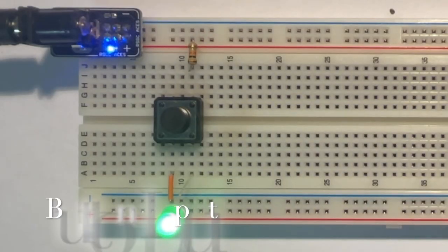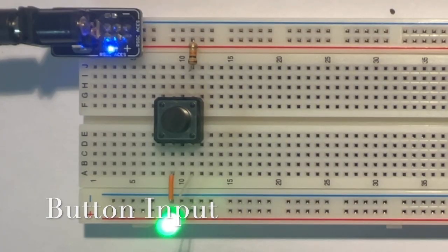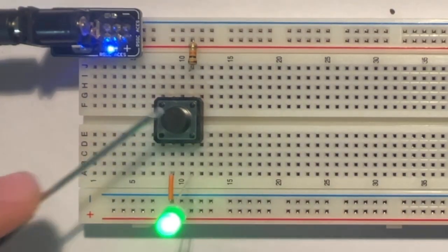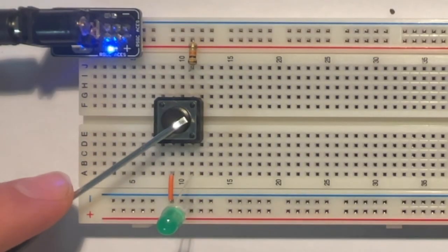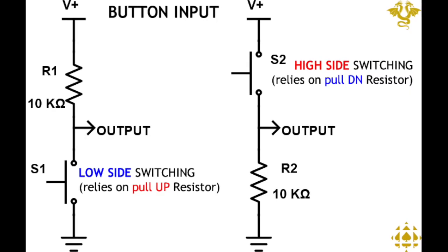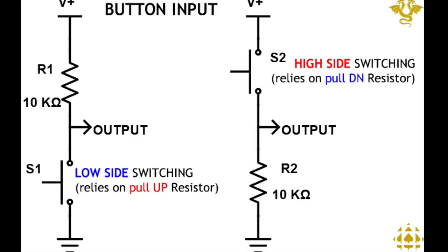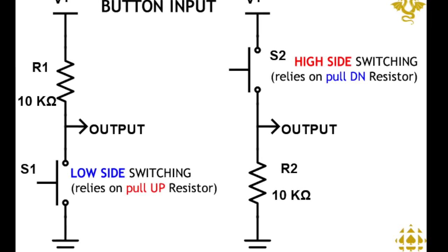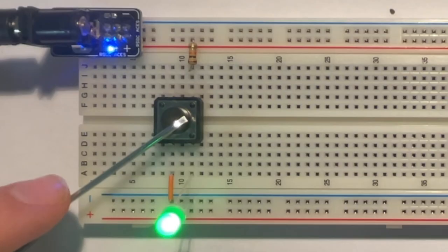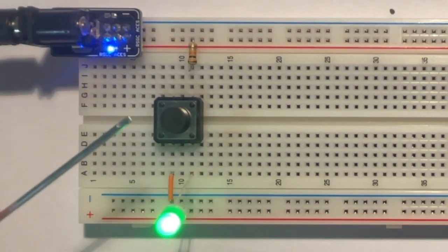The circuit begins with the momentary push button input, also called a PBNO. When this button is not pressed, the circuit is open and no current flows. As soon as it is pressed, the circuit closes and sends voltage to the NAND gate oscillator, starting the entire counting process. The button is wired in a pull-up resistor configuration where one side of the button is connected to ground and the other is connected to an input pin with a resistor pulling the voltage up to supply level. When the button is open, the resistor keeps the input high. When pressed, the connection to ground brings the input low.